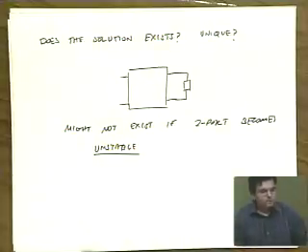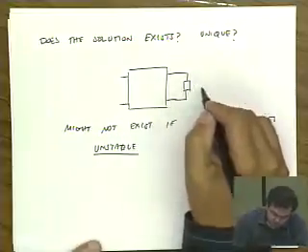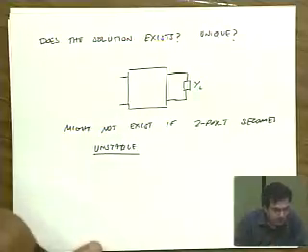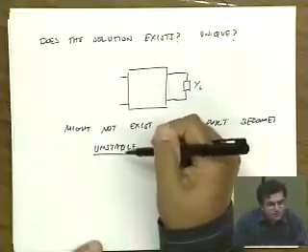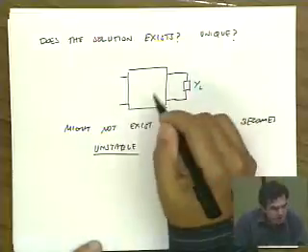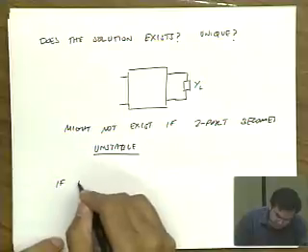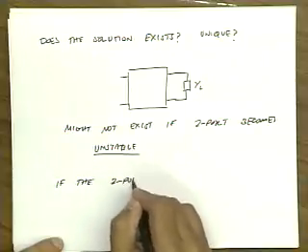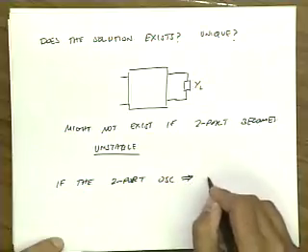We haven't really talked about stability at this point, but just intuitively, if I present a certain YL here that causes the output to oscillate, then clearly this solution for maximizing the power gain, transducer gain, does not exist. In fact, if the two-port oscillates, that implies infinite power gain.